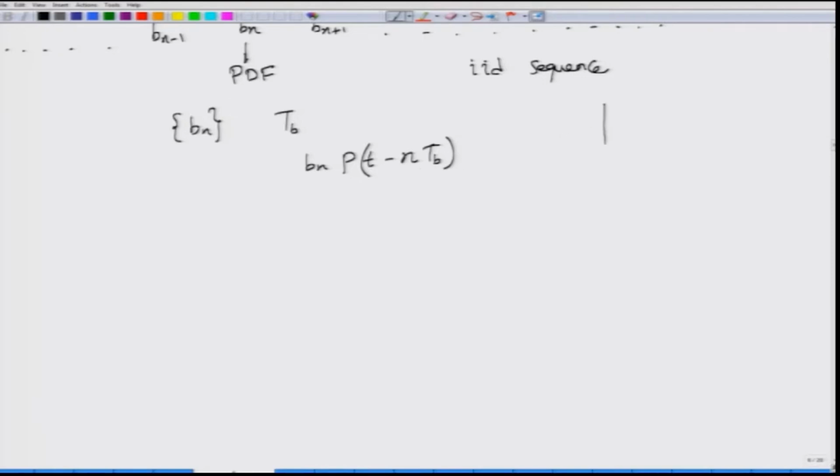From your signals course, you might know that if this is a basic pulse shape, let us call this time t, and let us say this is TB by 2, this is minus TB by 2. Here I am showing you a rectangular pulse. If you are fancy enough, you can have a different pulse, it does not matter, but the duration of the pulse has to be within 1 TB units. Then, if this is P of t, what would be P of t minus TB?